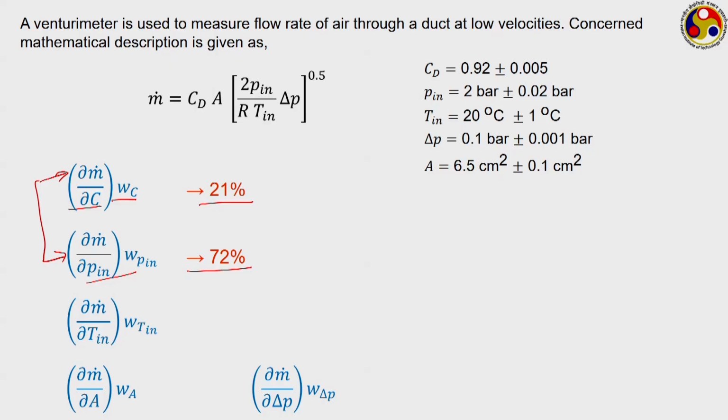Like in the previous example, we have seen a way of identifying the measurement method. Despite having to measure two quantities, it is better to go for both voltage and current measurement instead of only voltage measurement or only current measurement. Whereas in this particular case, there are 5 quantities where we are getting some uncertainty, but instead of trying to improve all 5, if we look at reducing only this particular uncertainty, then we are going to get the largest gain in the final output.